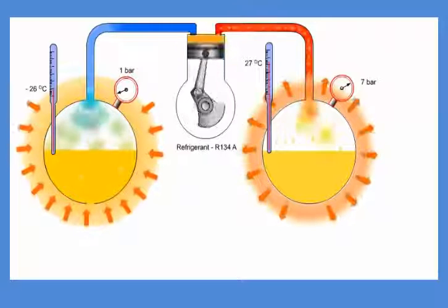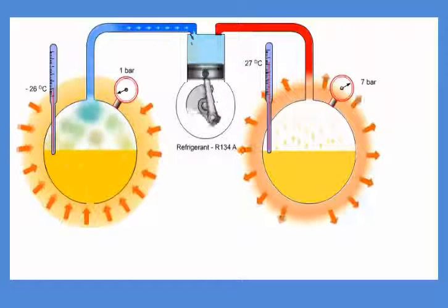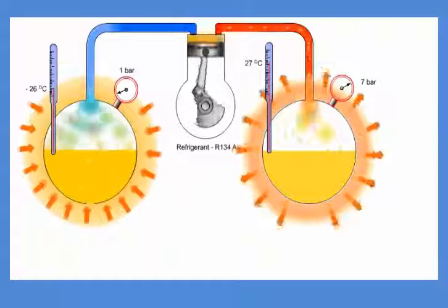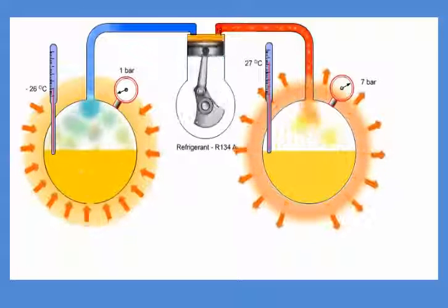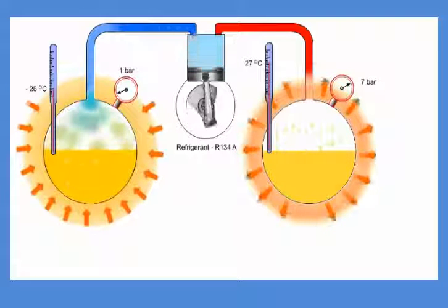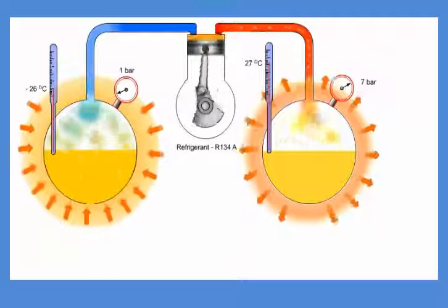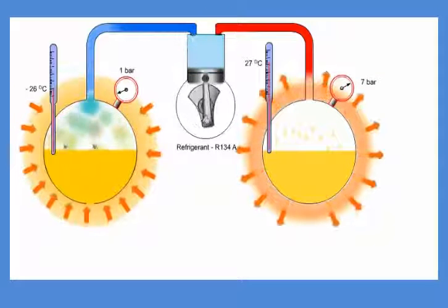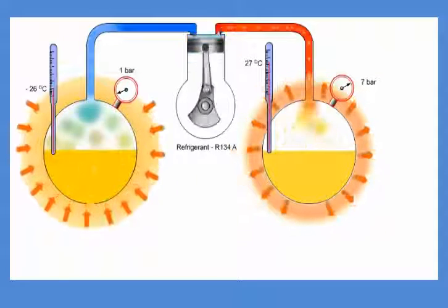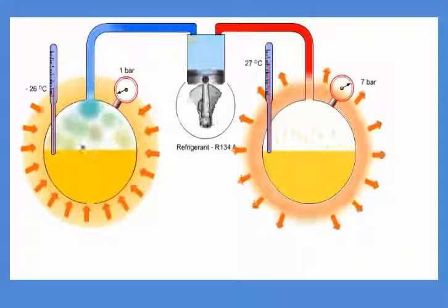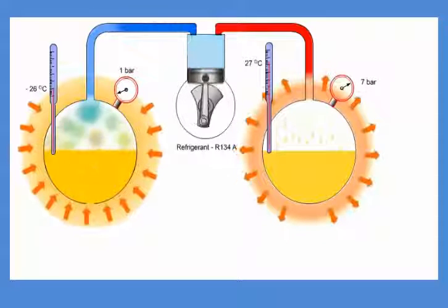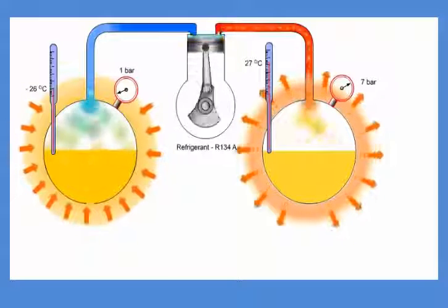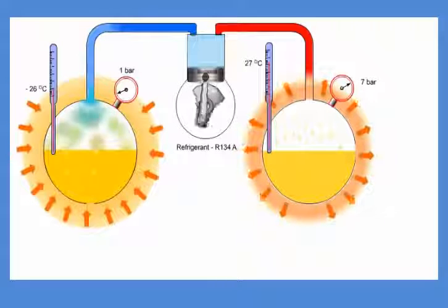A condensation process needs to give away energy in order to take place because the media, in this case the refrigerant R134A, changes phase from vapor to liquid. The vapor condensates. Liquid molecules have less energy than vapor molecules, so energy is subtracted from the media. This energy, in the form of heat, is given away to the surroundings.